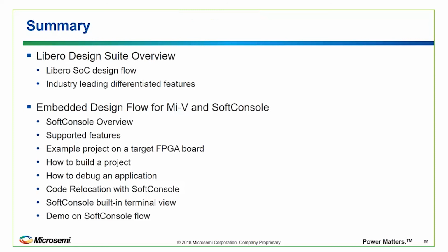But you could do the very same thing by creating a project from scratch, and if you created a project from scratch, you would have to use the Firmware Catalog to create your drivers in your RISC-V HAL, and you would have to go through all the project settings and then create your debug configuration. So the example projects are a really good place to start, since you can just sort of copy those settings when you create your project from scratch.